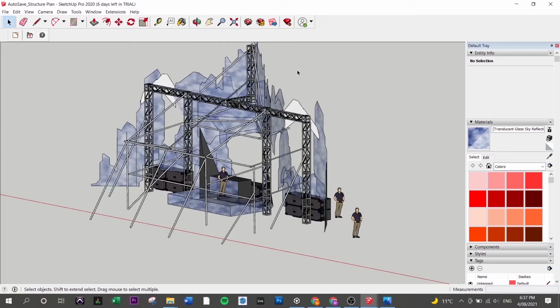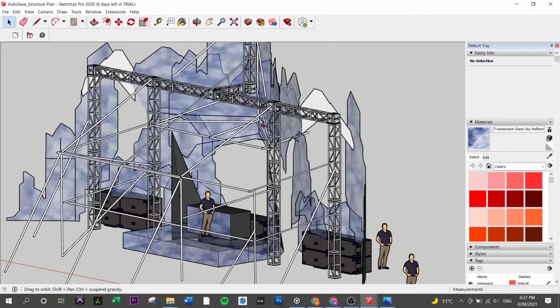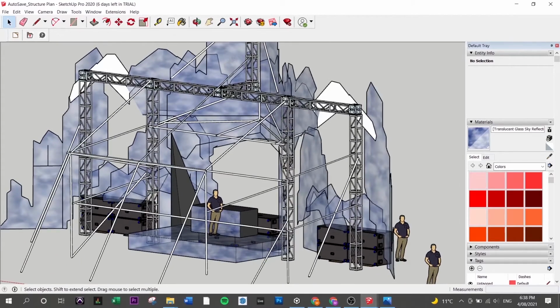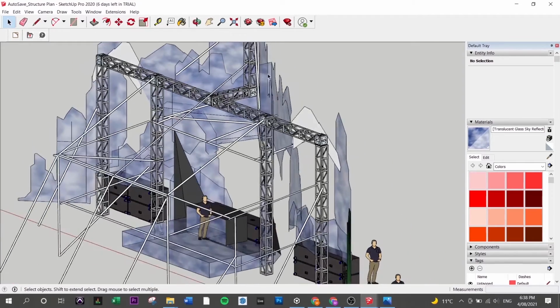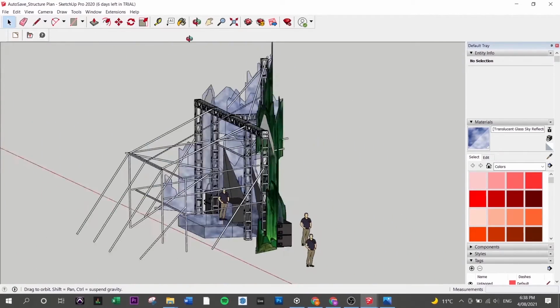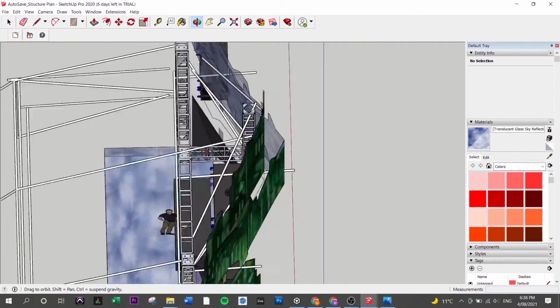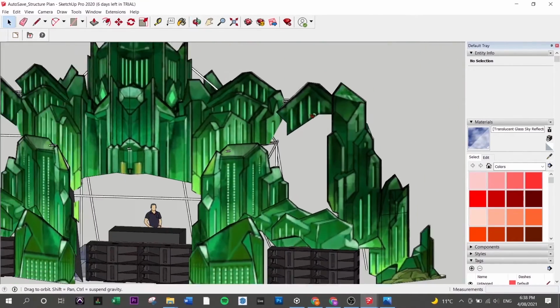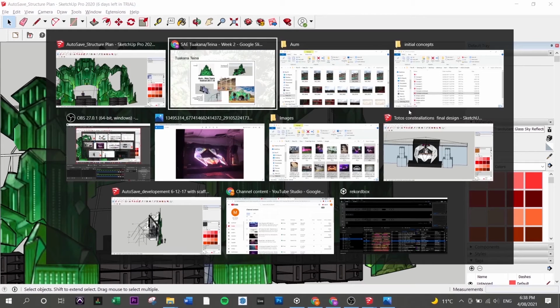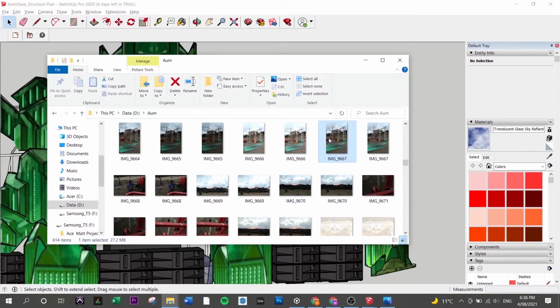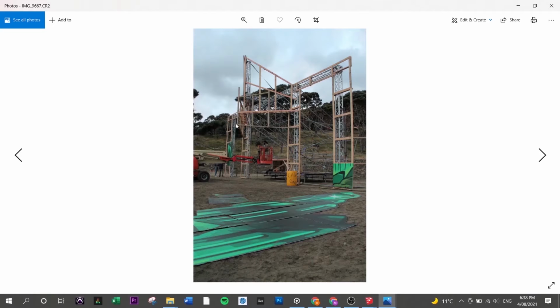So essentially what I instructed the people to do is we set up this truss according to the sizes that we had available. I built it all using 3-meter truss sizes with box sections with a cantilever out the front to achieve this front spire. We also wanted to layer it to have a gap to create a little bit more depth, and what we ended up achieving is being able to frame all of that out, as you can see from these photos.